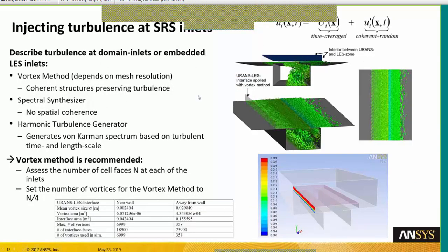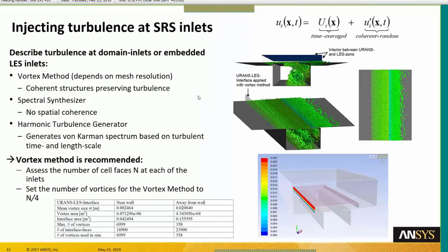So that is one of the questions you will ask yourself when you do LES, how to define the grid sizing. Here is another question that could be raised when you do LES calculation, and this is when your domain is limited in terms of extent. So at some point you will have some frontier of your computational domain, and at this frontier usually you will need to input, to feed some turbulence.